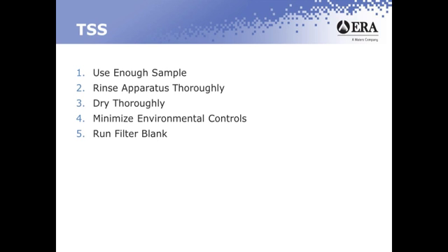The next topic we want to talk about is total suspended solids, or TSS. This is also known as non-filterable residue. So if you happen to see non-filterable residue on your reporting sheets or on your permit, we're talking about total suspended solids, or TSS. The biggest issues that we've seen with your TSS analysis revolve around controlling your environment, TSS being a sticky material, and ensuring that you can accurately measure your residue.